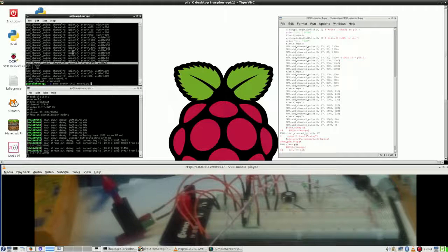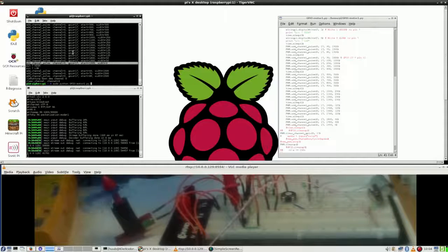So what I can do is change the multimeter to frequency. Then I have to remove the voltage ground probe and check for the frequency, which is 120 Hertz. And by experience I do know that that works. Now you see that the propeller stops and it doesn't do a thing anymore. Why is that?